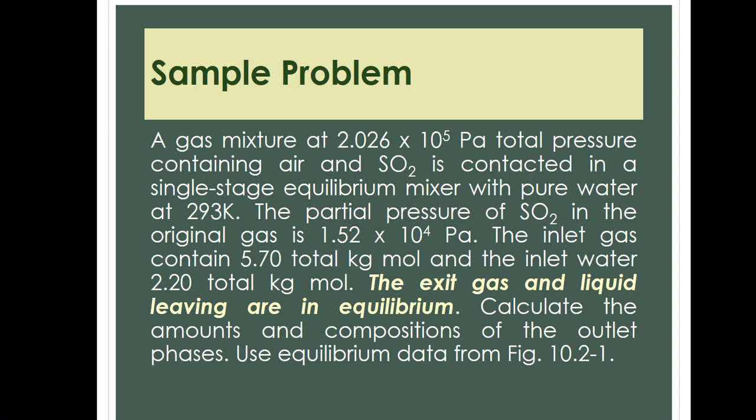If they are in equilibrium, the equilibrium equations like Henry's law and Raoult's law are applicable in expressing the relationship between the concentration of the liquid phase and the gas phase that leave a particular stage. So again, the equilibrium equation is only applicable for phases that are equilibrated. In this case, we are using it on phases that leave a particular stage or a single stage unit.